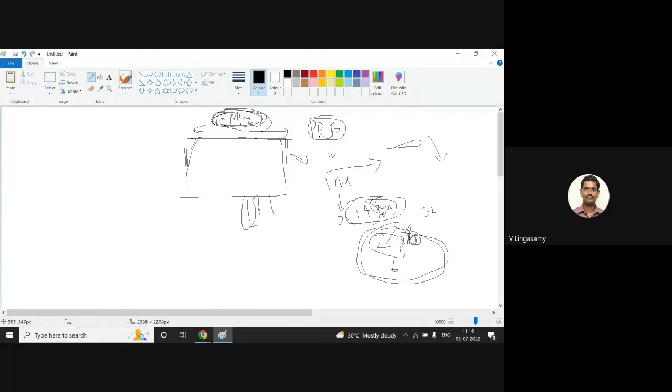You can do carrier aggregation as well. Instead of allocating 10 megahertz to one user, just for example, I allocate 2 megahertz, 5 megahertz, 3 megahertz to each user. That way you can aggregate the carriers. This will cater to some users, and that will cater to other users. This way we can achieve spectral efficiency, still with the same allocation.